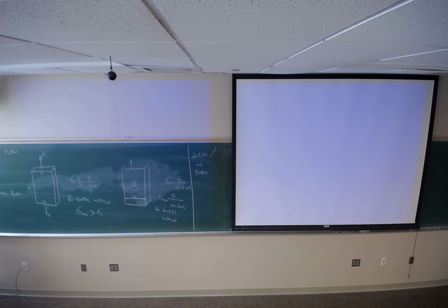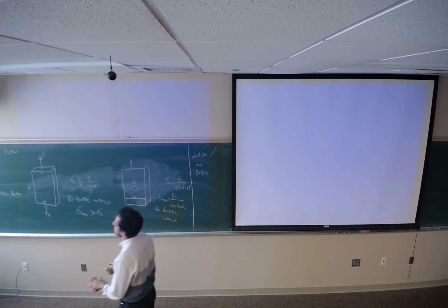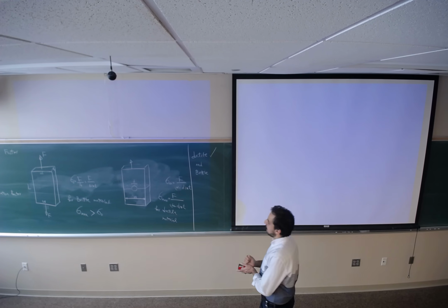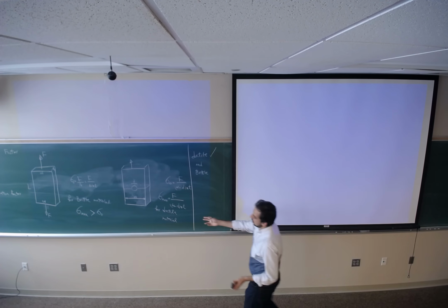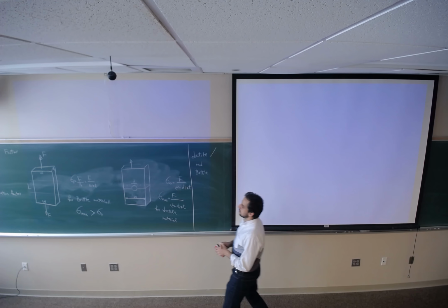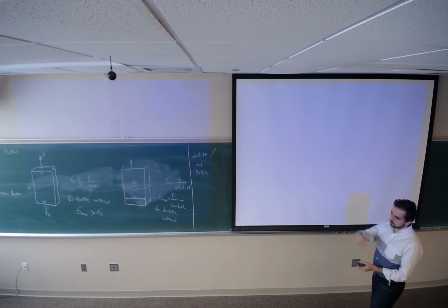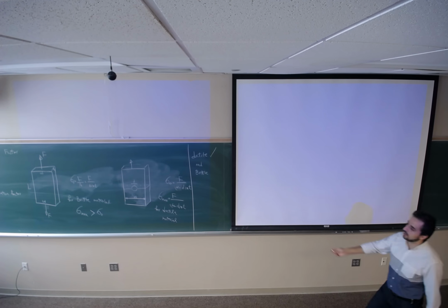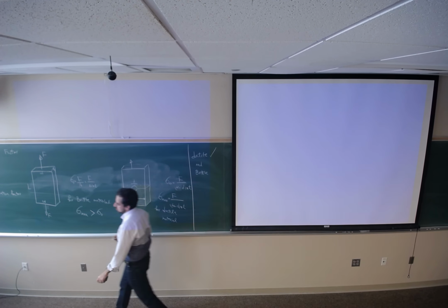KT is defined as the ratio of the maximum actual stress applied to this bar, divided by the nominal stress that is coming from the equation.